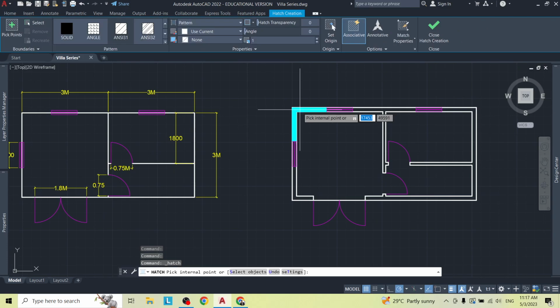It has to be shown using the hatch pattern to show that the walls were cut. So I'm gonna use this. Gonna change the scale to 1500. Let's see if that's big enough. Ooh, okay. All right. Yeah. So I'll have to change the thickness of this layer soon.